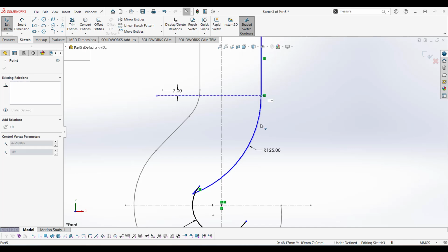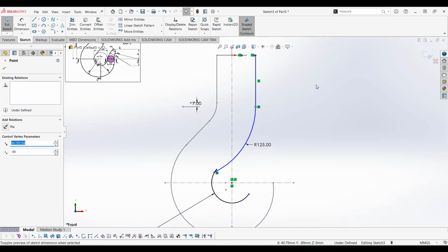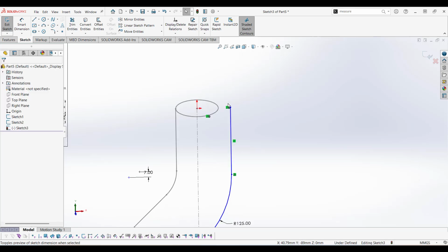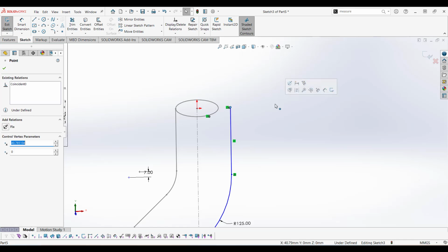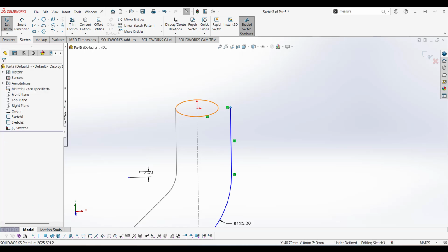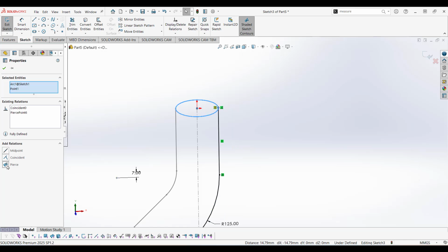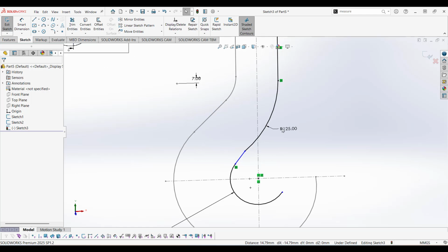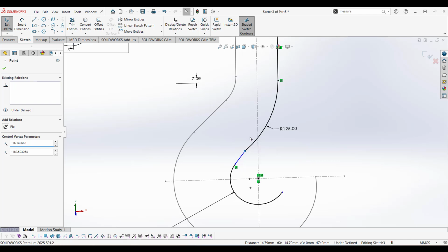And if I bring this line a bit, well, the starting point of this sketch should be coincident with that curve. So this is one condition you have to add. And just by picking this point, holding the shift, selecting that curve here, now you can make them pierced. That brings your sketch to the right position. Alright, so now all you have to do is make this end tangent, the other end is already tangent. So hold right click and make a tangent relationship.